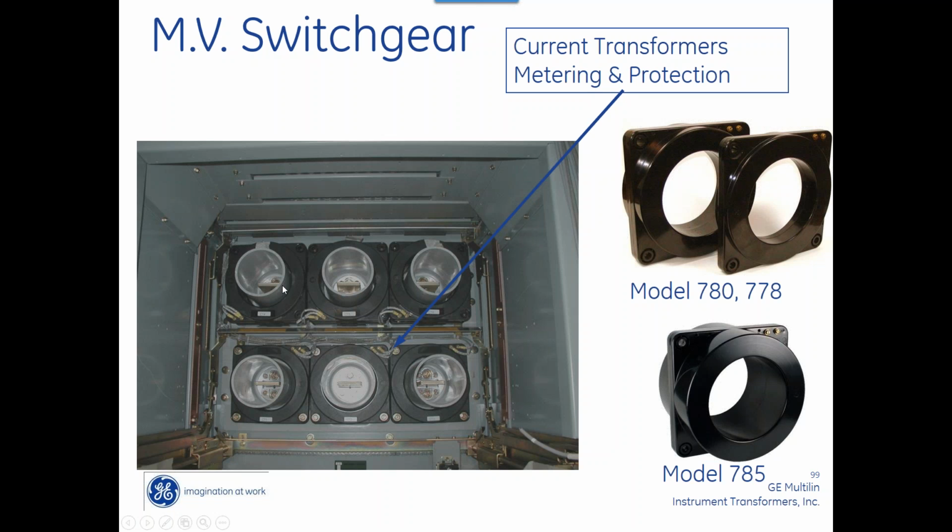Stack them on this. Yeah, so here's a good application where I could stack the CTs. See how the 780 is much thicker, 785 I guess, versus the 780. So that's all a factor, and you just have to talk to the manufacturer about whether it'll fit. But yes, you could stack them.